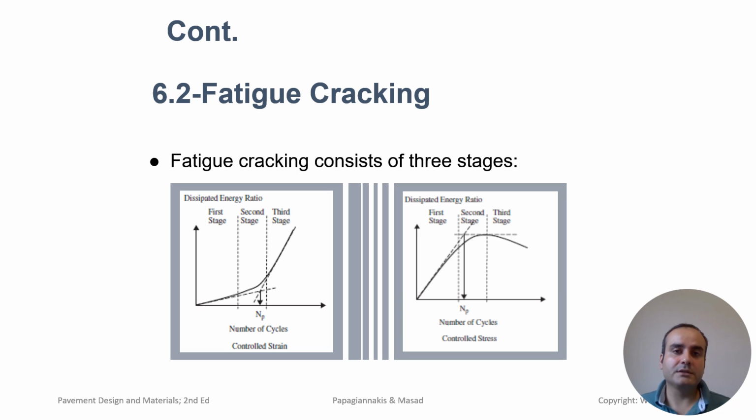In the second stage, the microcracks that formed in stage 1 start to propagate upward toward the surface of the pavement. As the cracks grow, they combine to form larger, more visible cracks, and the propagation of cracks is accelerated by continued loading, especially in areas with heavy traffic or overloaded vehicles. In addition to traffic loading, temperature fluctuation can also influence the speed of crack growth, as cold temperatures make the asphalt more brittle and prone to cracking.